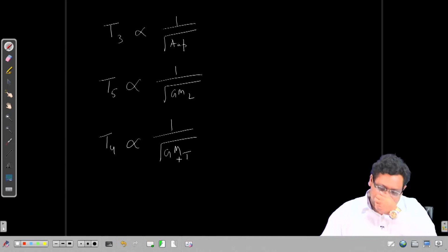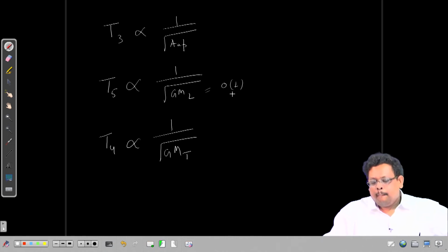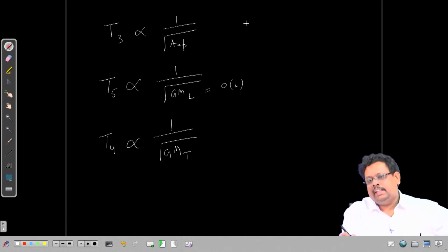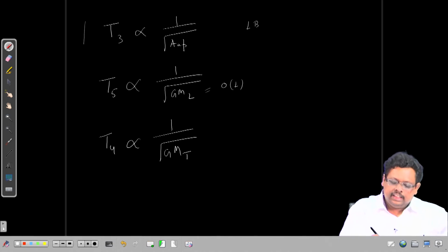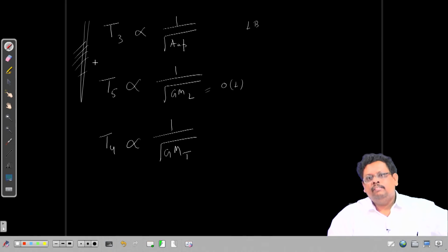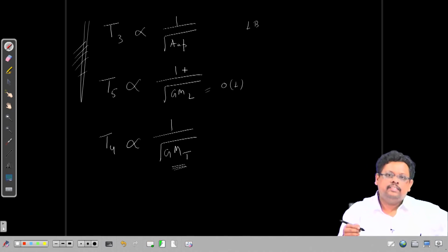Now, what I am trying to say is as follows. Now, GML is much higher, it is of the order of length, right. And then you can see the water plane area also, let us take a rectangular barge, it is also L into B, right, something like this. So, these two fall in more or less the same range. Okay. However, you can see that GMT is much lesser compared to all these values.